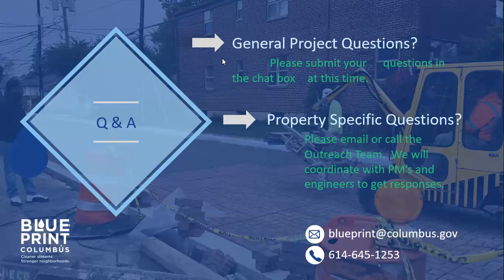So the design sewer reliefs, is that what he's asking? They're not located immediately adjacent to any of this work, but there's a few located within the North Linden area that directly discharge to storm sewers, which are directed to the river. I'm sure we can provide a map indicating where the eventual outfall is. Those maps that I was showing you the other day, Tiffany, just show where the overflow from the sanitary to the storm sewer is. It didn't illustrate the eventual outfall at the creek. I can track down those maps and provide those.